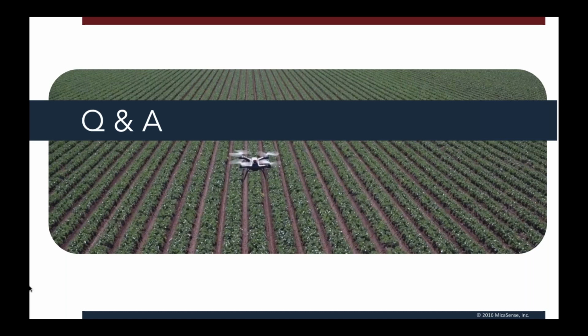Someone says, which are the correct parameters to fly with Red Edge MicaSense? What overlap and side lap can I use? So one pretty good rule of thumb for flying with a Red Edge to get appropriate side lap, and side lap is generally going to be the one that's most affected by your mission planning, and I think that's what this question is geared towards, is to make sure your pass width is 1/4 of your AGL.